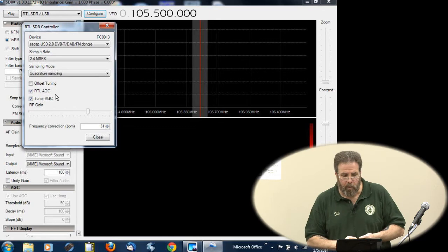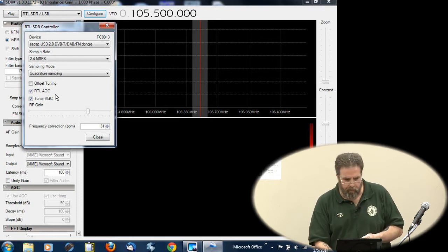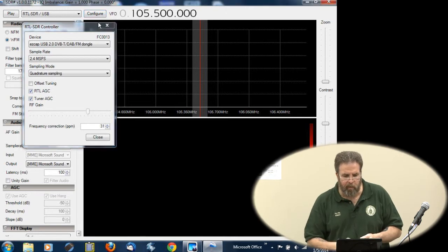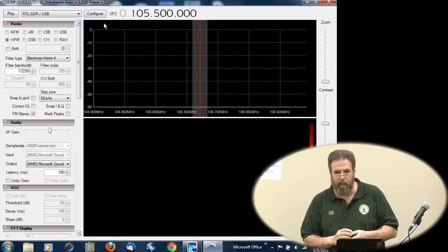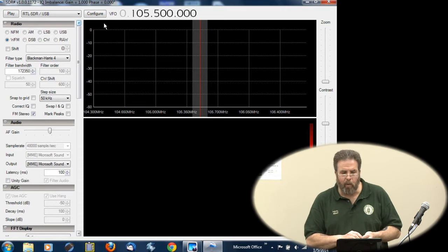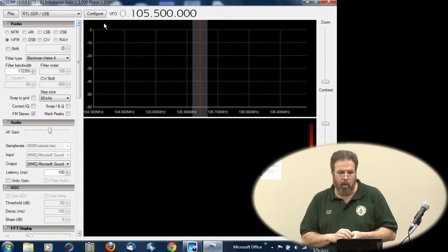Okay, thanks. I'll take a look at that. Sure. Like I said, I can look at the broadcast band, listen to AM, FM sounds great, decoding codes that come in. You've got to watch these modes too. If you're trying to listen to 2 meters, 440, you have to be on narrow FM. And then if you go into the broadcast band, wide FM.